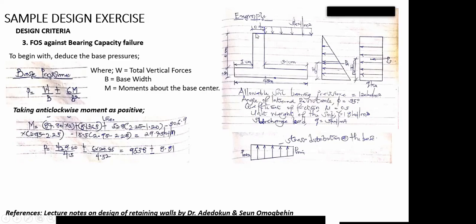Now, this one is the vertical. This vertical wall, this vertical stem, we've done that, and the second one is the vertical force. Don't forget that we've taken the horizontal aspect of our soil, which is this 87.81 that gave us lateral earth pressure. Now, the vertical aspect will also take moments, and we got 306.9 to be the vertical force of our soil, acting at this particular point, which is supposed to be 1.55 if I'm not mistaken.